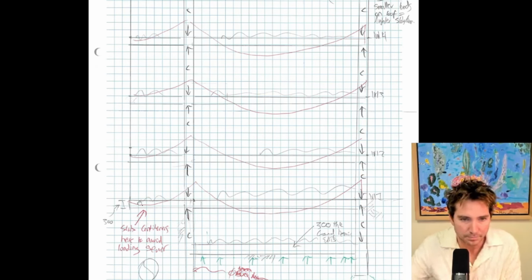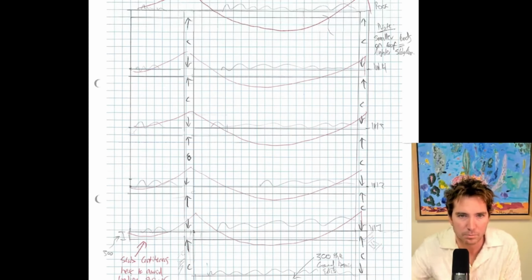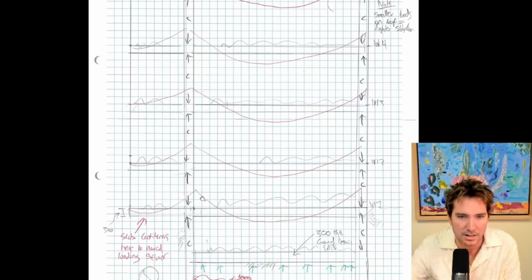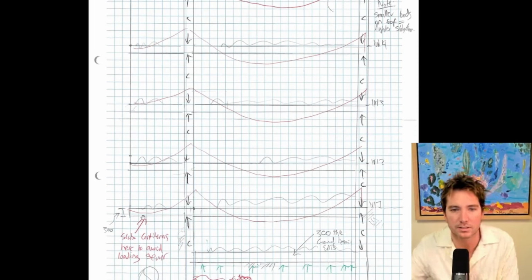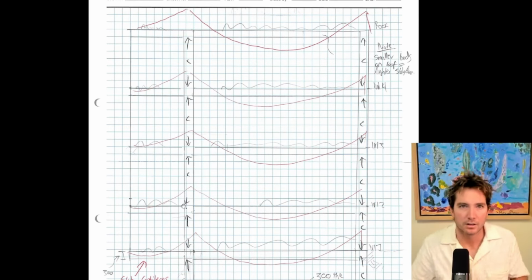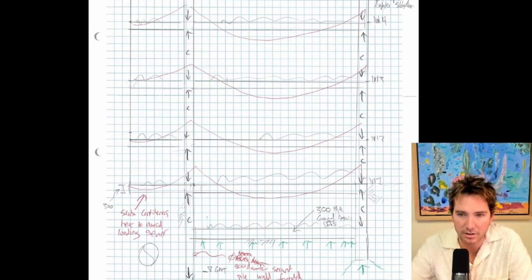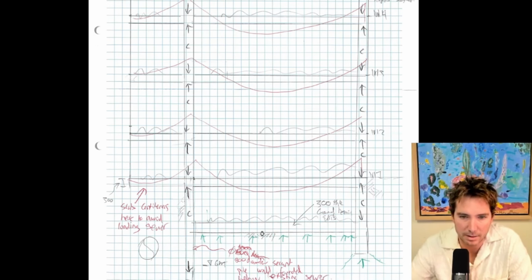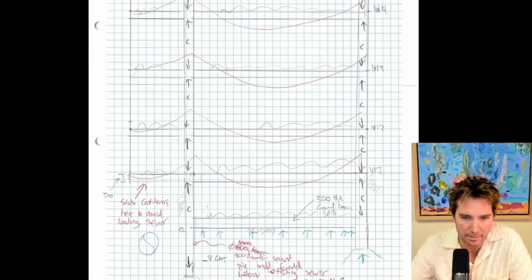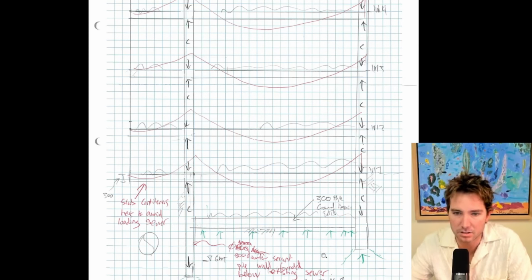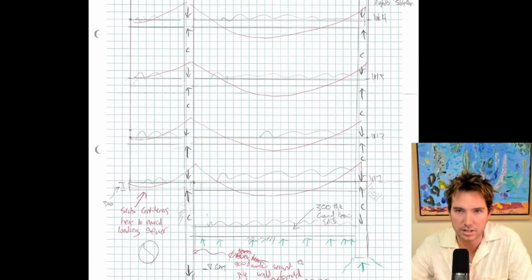So as I mentioned before, I'm cantilevering past pretty much all my band beams here, and that's key down at level 1 because I can't load this existing sewer. So I'm illustrating the vertical load path of my structure here. Then in the ground, it's essentially just a ground bearing slab, 300 thick. And I'm showing my secant pile walls, where it bears onto the ground, avoiding completely that existing sewer. So that's a little sketch of the vertical load path.